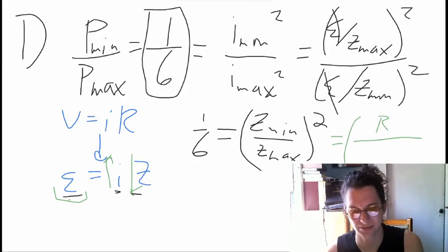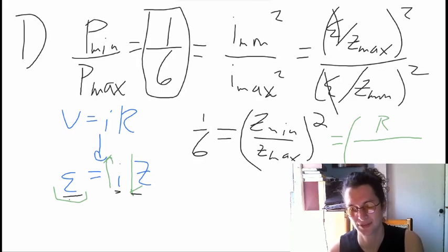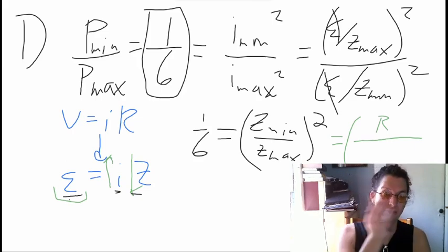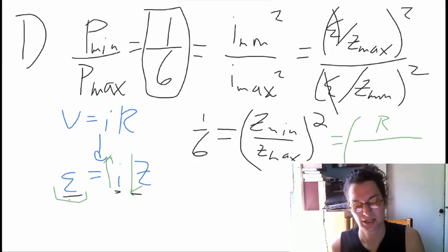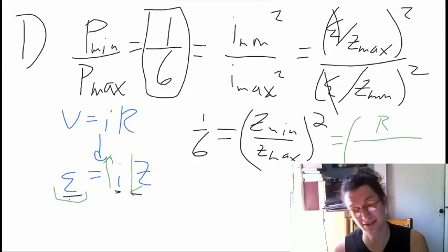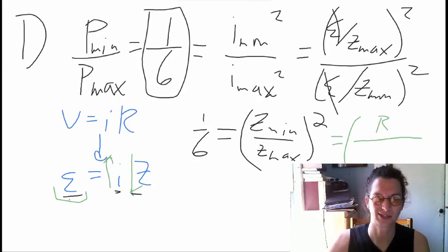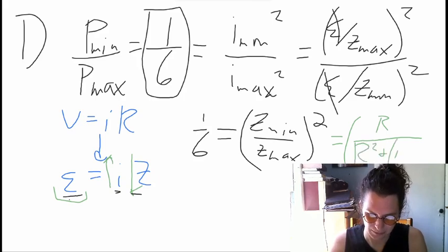Our maximum impedance will be at the current that's given, the maximum inductance as well at that point. Now keep in mind the way that we add these together, going back to the last chapter, is that resistance can't just be directly added to omega L, which is the reactance of the inductor. They can't be directly added. Remember, we had to add them in quadrature because they are 90 degrees out of phase. So that's why you end up with this guy here, R squared plus omega L squared.